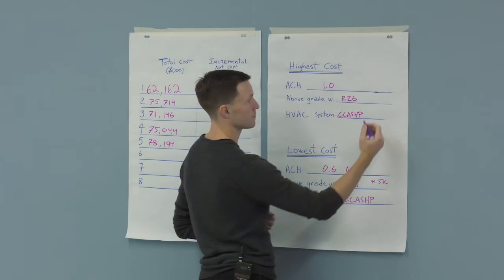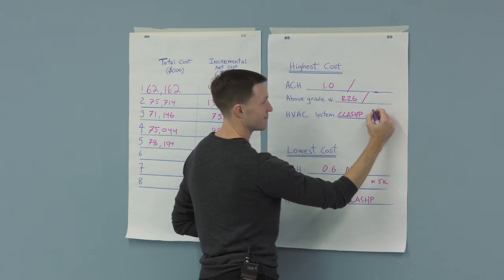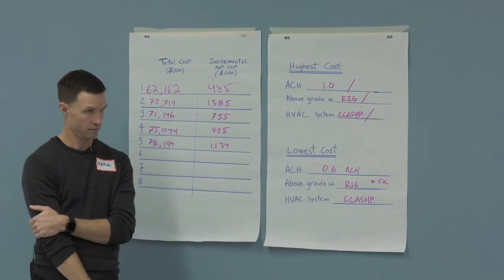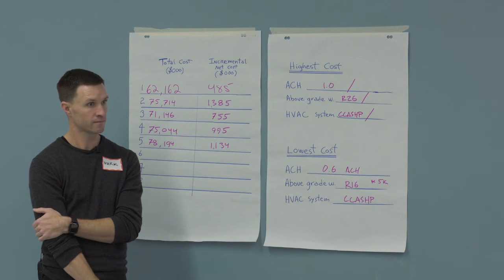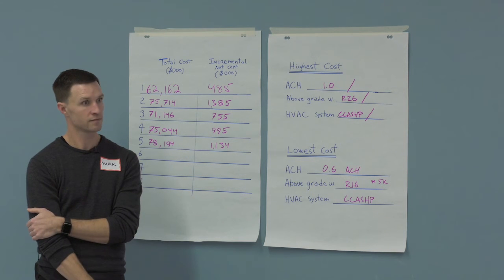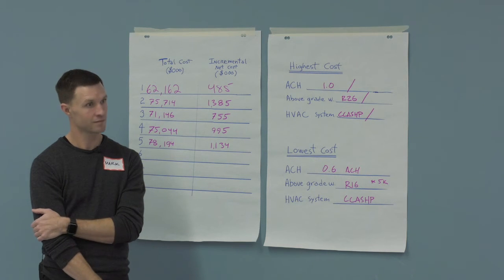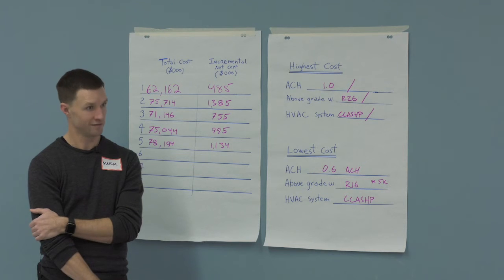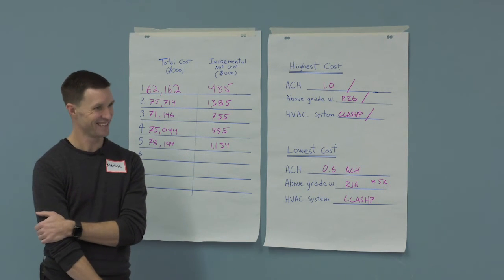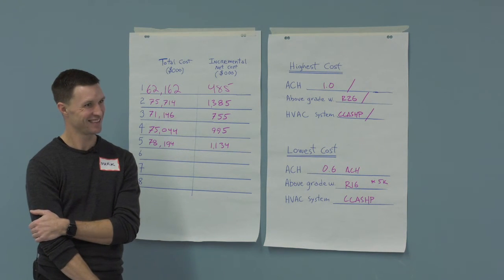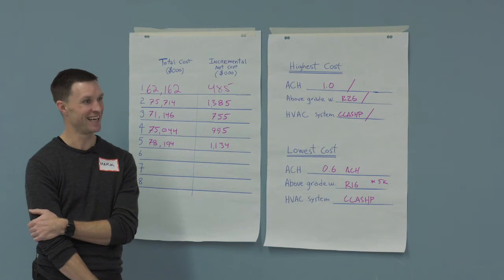I looked at the results that we'd got previously and made sure I kept the options that had been selected as cost efficient to begin with. And then when we came up with the first set of results, we changed to try and see what we could make a bit better. But the one thing that we did keep was we tried to put in low gain windows because we don't like high gain windows. And what was it that you were particularly caring about? There was some aversion to gas.